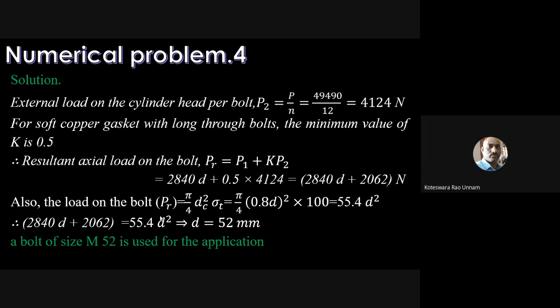Our rivets also have some diameter. Here we will take the bolt's nominal diameter alone while designing the bolt. So whatever analysis we carried out in the case of riveted joints is applicable here also. That means we already know the procedure for analyzing a bolted connection when it is subjected to eccentric load.